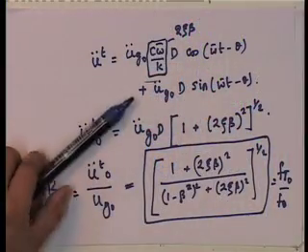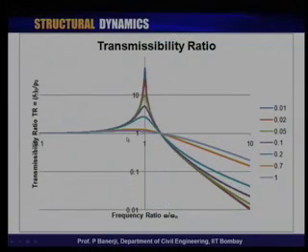And the other one is essentially transmission of a force from a machinery to the base. Okay. So, one is force transmissibility, other is acceleration transmissibility. But note that mathematically both give us the same transmissibility ratio, which I had looked at yesterday in terms of force transmissibility, and today the same equation again is valid.